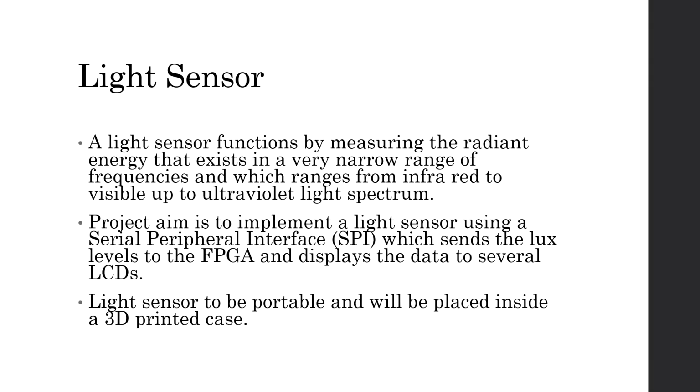Hi, my name is Josh and I was responsible for implementing the light sensors of the project. A light sensor functions by measuring the radiant energy that exists in a very narrow range of frequencies, which ranges from infrared light to visible up to the ultraviolet light spectrum. The design intent for the light sensor is to connect to the FPGA through serial peripheral interface and have a lookup table to convert the readings into lux.